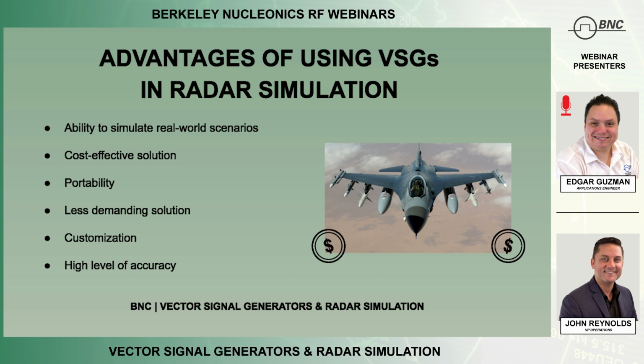The customization, I think John mentioned it previously. There's a plethora of options, especially on just our 875, and we can tailor the VSG specifically to your application needs. So if you don't need 40 gigahertz and you only need 12, you can go for that. You need lower noise, fast switching. If you're doing multi-channel, you need phase coherent switching or phase coherent channels. That's another option.